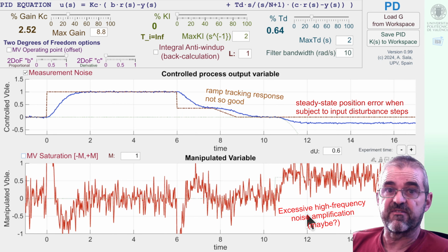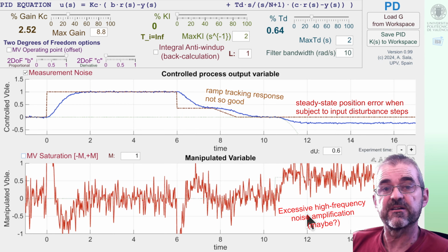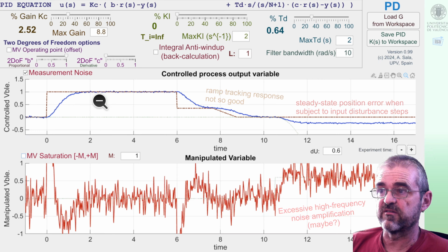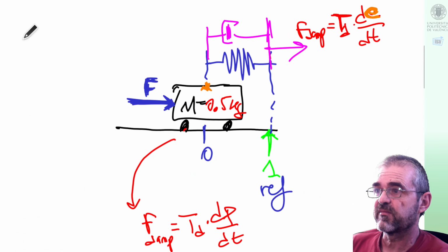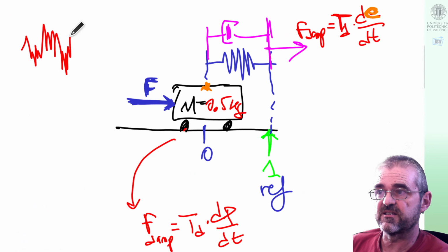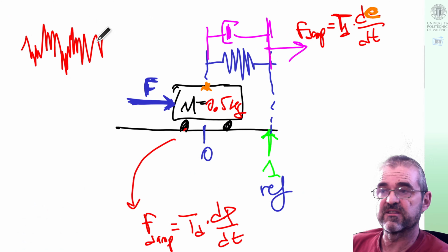Proportional control amplifies noise by the proportional gain, but derivative control exacerbates that effect because, if we zoom in, the signals with noise have fast changing slope, so the derivative is 200, minus 1000, or whatever.